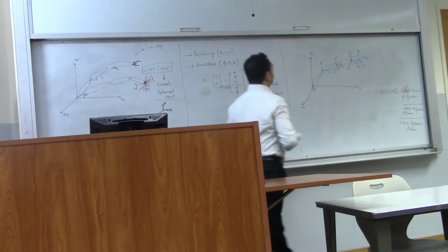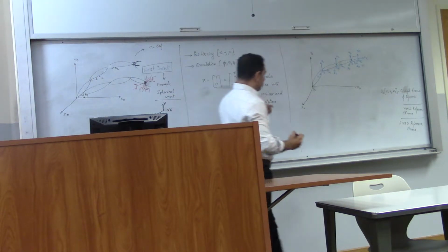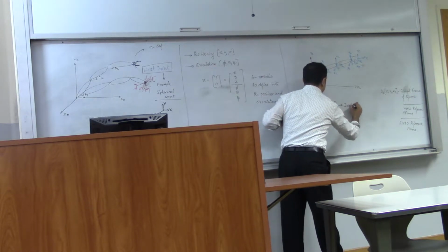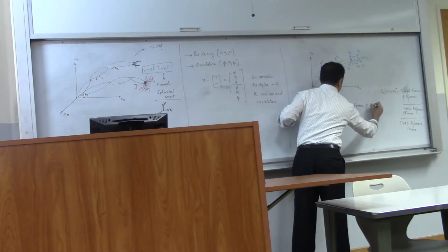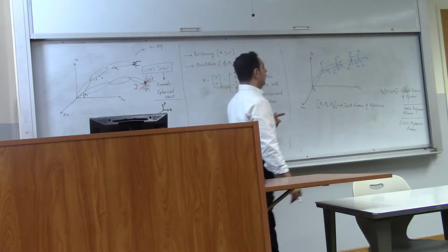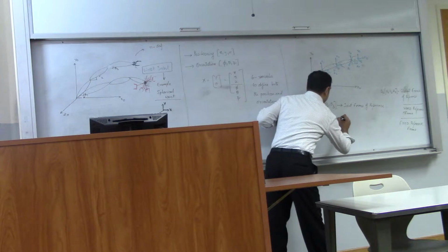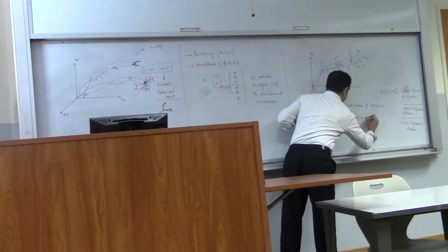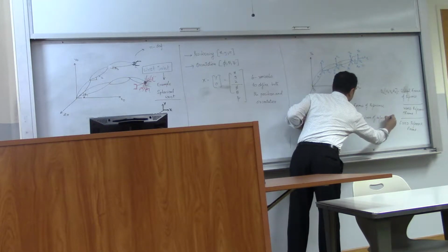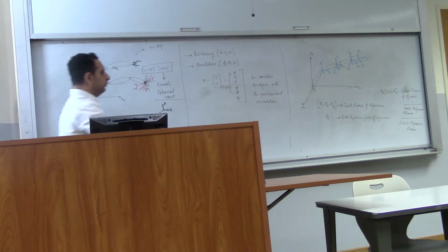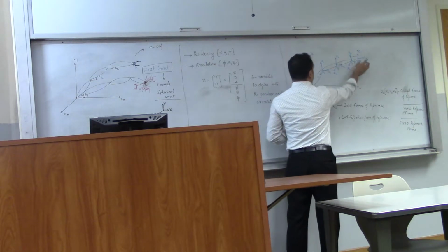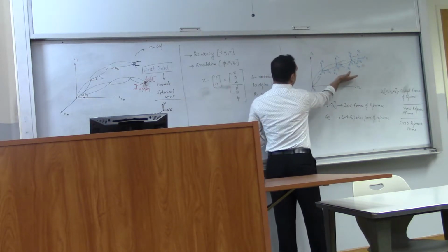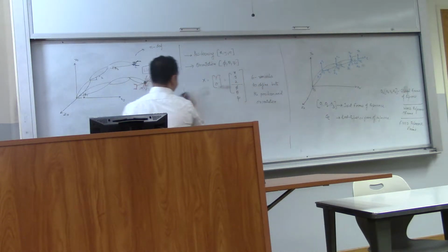This is O0. Okay. So O1, O2, O3. These are joint frames of reference. Okay. OE is your end effector frame of reference. So when I generate any motion about this, the origins of all other frames will move. Okay? If I change O3, only OE will be affected. If I change O1, or from here, any motion from O0, all these frames will move up or down depending upon the relative motion between them.